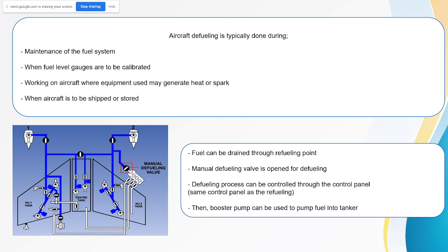The defueling process is usually followed by strict regulations to reduce the risk and maintain safety, such as the aircraft must be at a certain distance from any building before defueling, and also the staff are prohibited from smoking and so on.